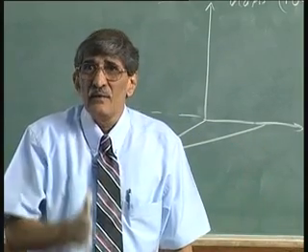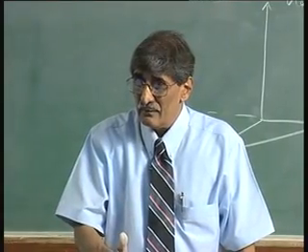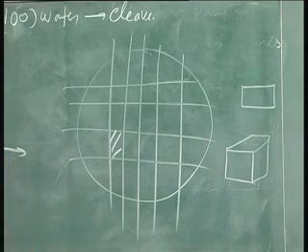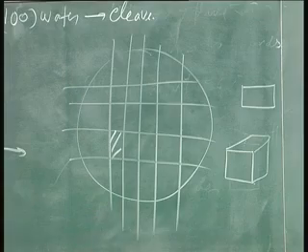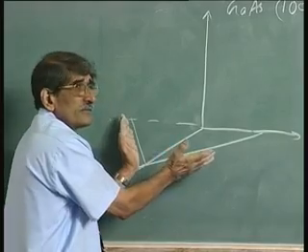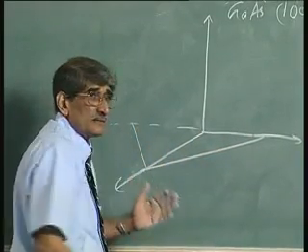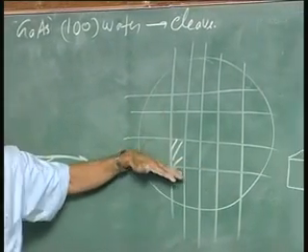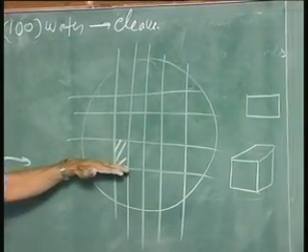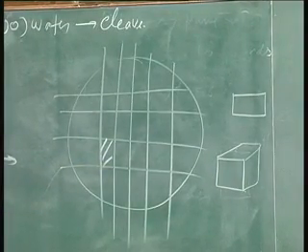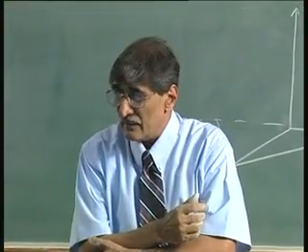The property that 110 plane is perpendicular to 100 plane, I can scribe along the 110 direction like that, both are perpendicular, 110 and 11 bar 0 on the xy plane, both you call it as 110 direction. If you call 110, that may be 1 bar 0, they are perpendicular. So, there the planes are vertical, and that is the key advantage of having this material for this application.